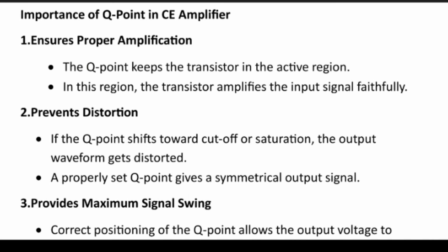So what is the importance of the Q point in a CE amplifier? The first point is that it ensures proper amplification. If you keep the Q point in the active region of the transistor, the transistor amplifier will take the input signal faithfully.